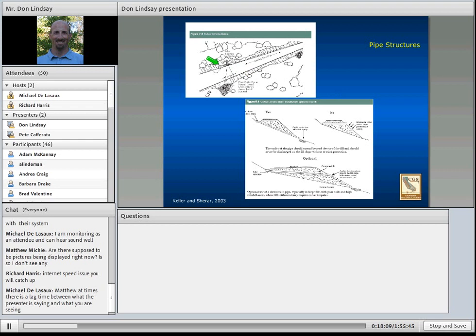cross-drain pipes are typically oriented about 0 to 30 degrees perpendicular to the road, are inclined to match the native slopes, or are placed in the fill with a downpipe and/or energy dissipator, shown here. Cross drains should never be placed to discharge onto a fill slope that is not adequately protected.